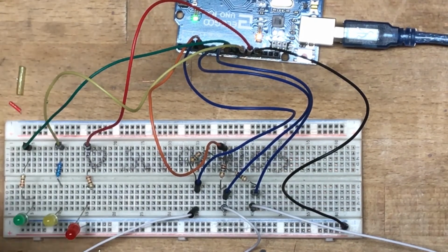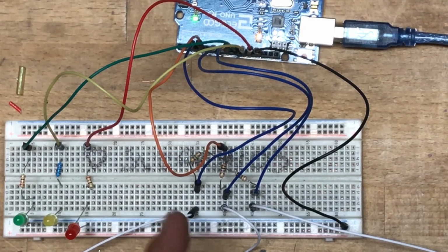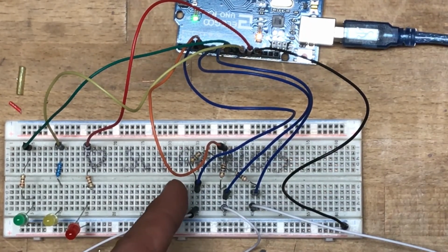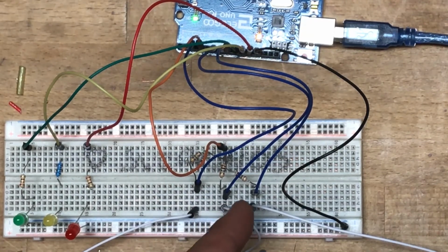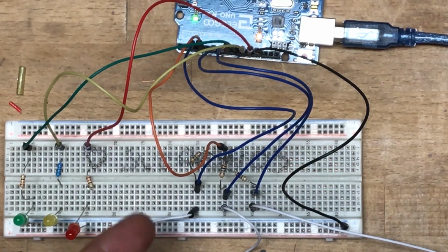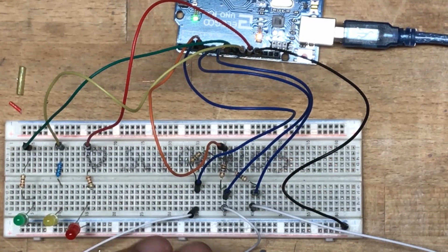That's the simpler part. The other side here, we have our 3 high ohm resistors, 4.7 mega ohms, 10 mega ohms, 1 mega ohm. These are just ones I'm using in this example. You can change this up as much as you want. The higher the value of that resistor, the more sensitive it is.